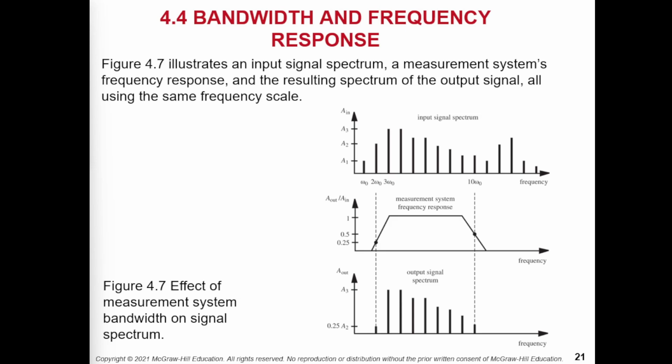But if you move both corner frequencies closer together, then finally it will become a frequency response like this. So after you invert, you need to decrease the bandwidth, and eventually you can get a very deep attenuation at a certain frequency, for example, 60 hertz, and this is what becomes the notch filter.